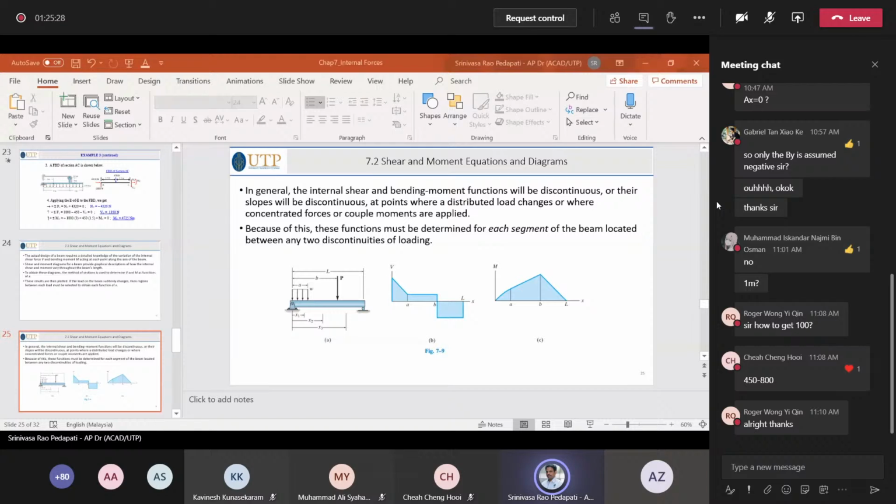So where there is not much requirement, we try to reduce the weight by reducing the thickness or diameter at the top. Similarly, road bridges are tapered, because a tapered beam reduces the weight. At the same time, you should take care of the loads that are coming onto the beam. So that is the reason.